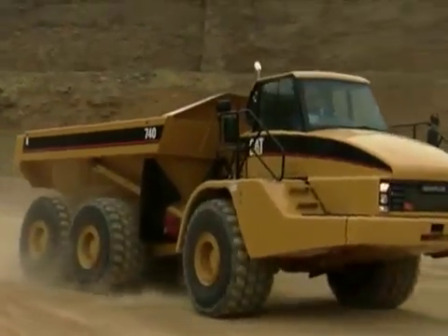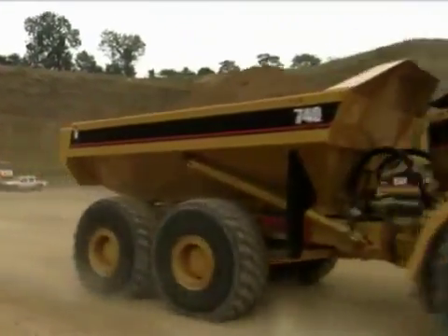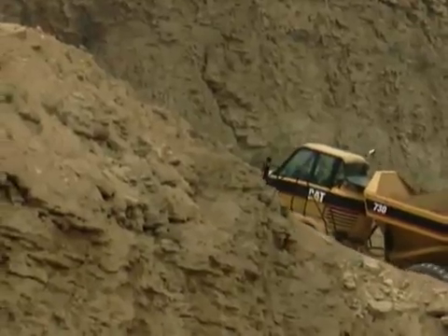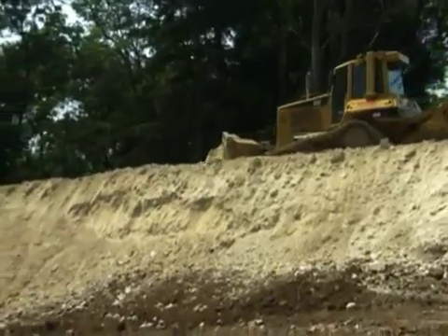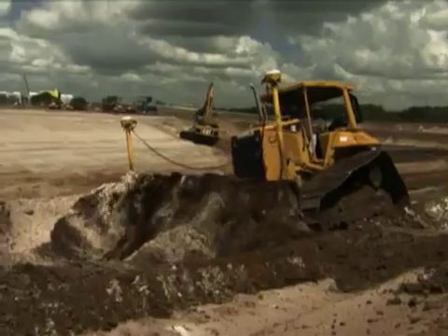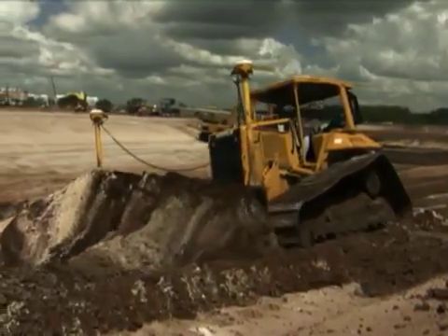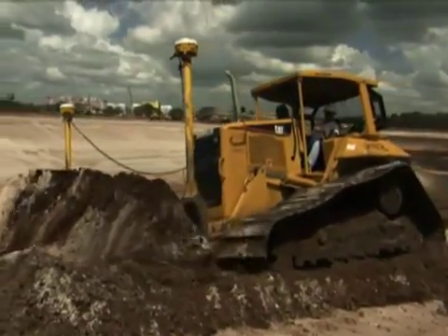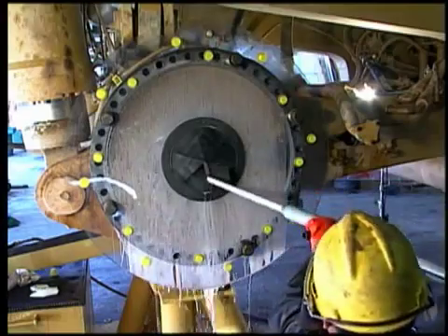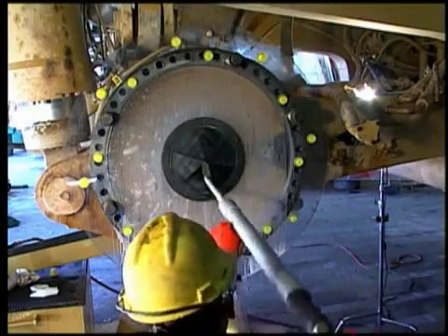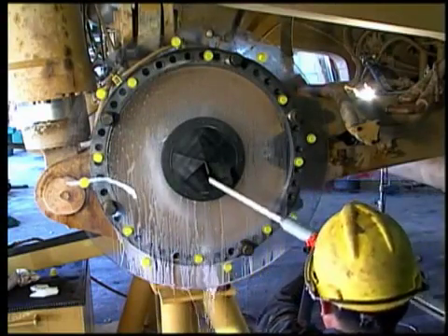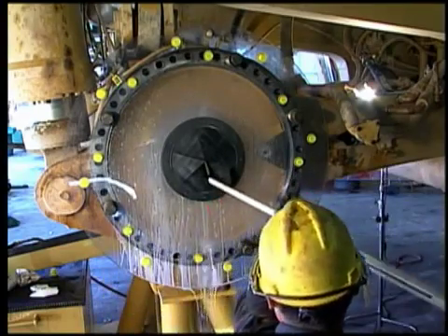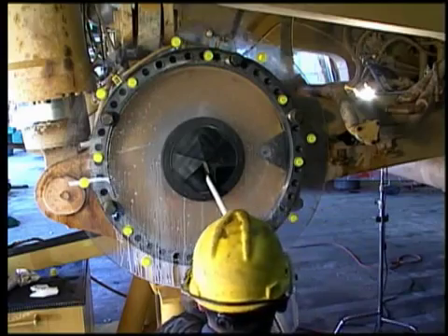For example, contamination can affect the control valves that regulate the amount of oil going to the clutches in transmissions. Contaminants can make the valves stick or plug the orifices. That will result in harsh shifts or the inability to shift. If the differential housing isn't properly cleaned when new or rebuilt final drives are installed, the remaining contamination in the housing will contaminate the final drives, causing leaks and premature wear.